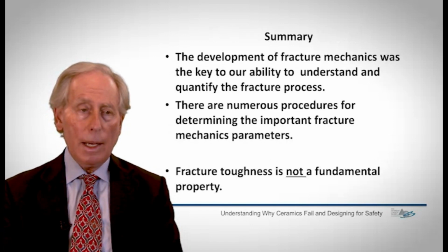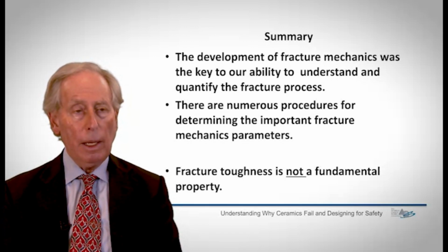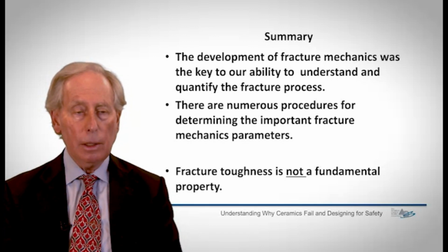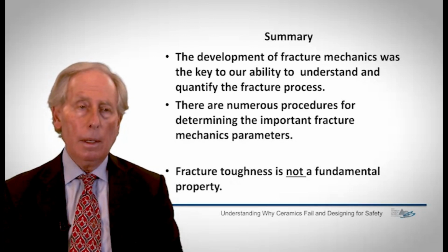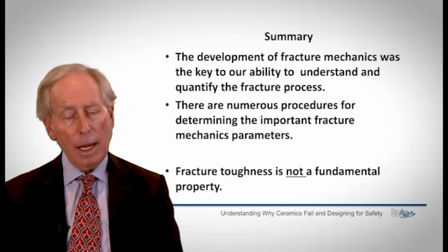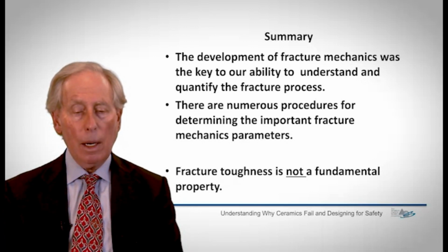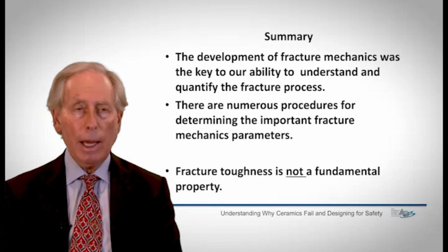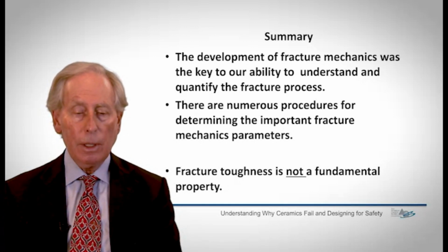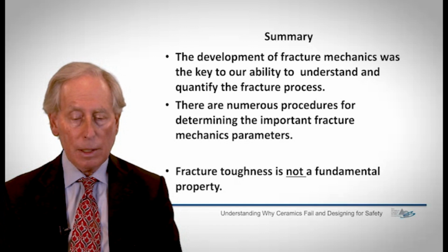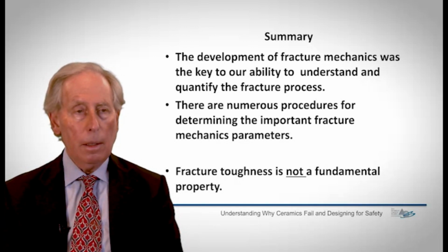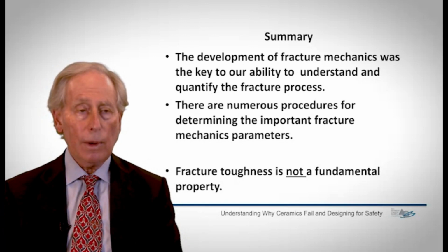Let me just summarize then what I think we've talked about a lot during this particular chapter in the series of lectures. One, I think most important, just get this idea across that the development of fracture mechanics was the key to our ability to both understand the fracture behavior, to understand the physics of fracture, and to quantify the fracture process. I showed a number of procedures for determining the important fracture mechanics parameters, particularly critical fracture toughness.